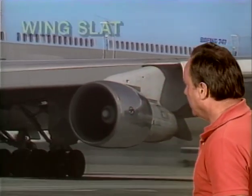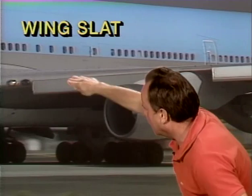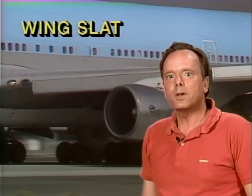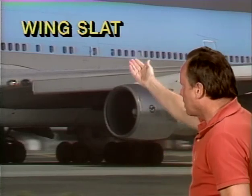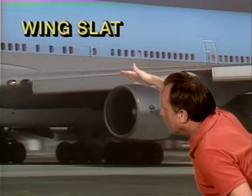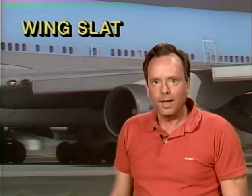Now, you might ask, we talked about slats. What is a slat? Well, a slat is a movable airfoil on a big airplane like this one here, and it's a movable airfoil at the front of the wing, like so. So there you see a slat, and it's attached to the leading edge of what they call high-performance wings, and the purpose of the slat is to reduce the stalling speed. So it moves forward, and it normally leaves a little space for air to get through, and it changes the shape of the front of the wing, and that's why it's called a slat and not a flap.